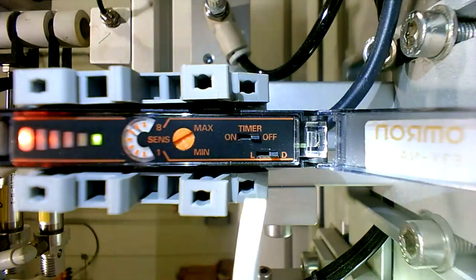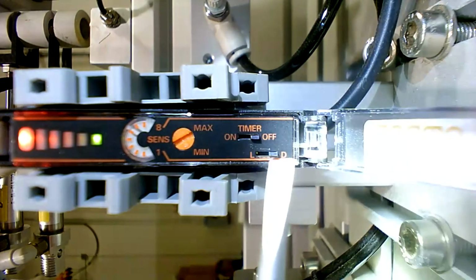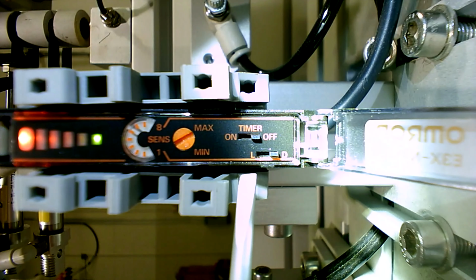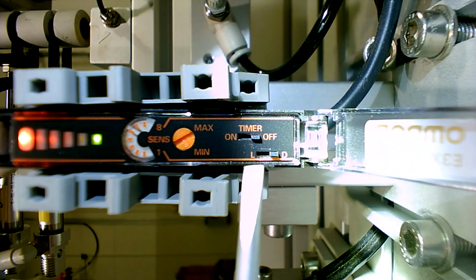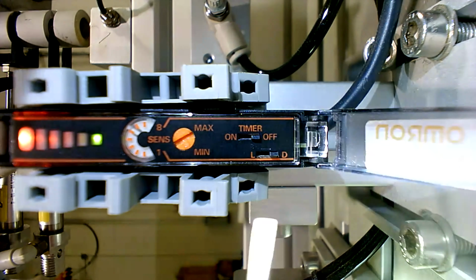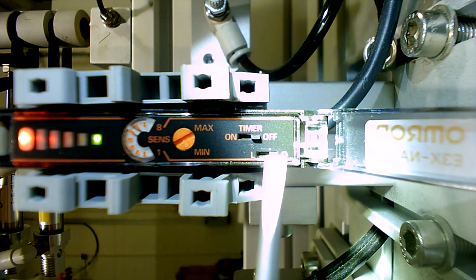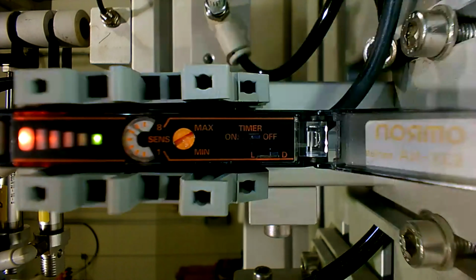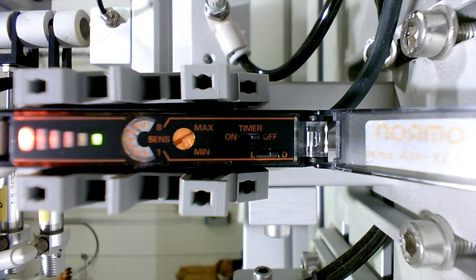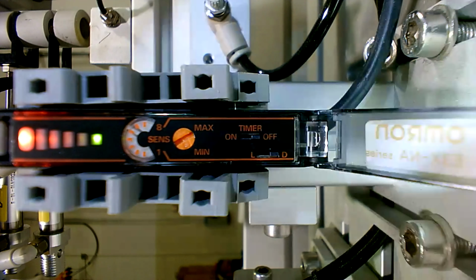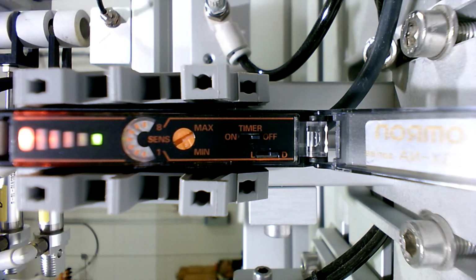And then, let's say on a garage door, what mode would I need that in? Light or dark? Light. It had to be on L if it was a garage door, because you want to see the beam across the bottom of the door before the door can come down. In this case, you're looking for a screw to be in the hole, so you want to see it dark. So dark sends out 24 volts when it's dark, not when it's light. Everybody got it? That is a very important detail.